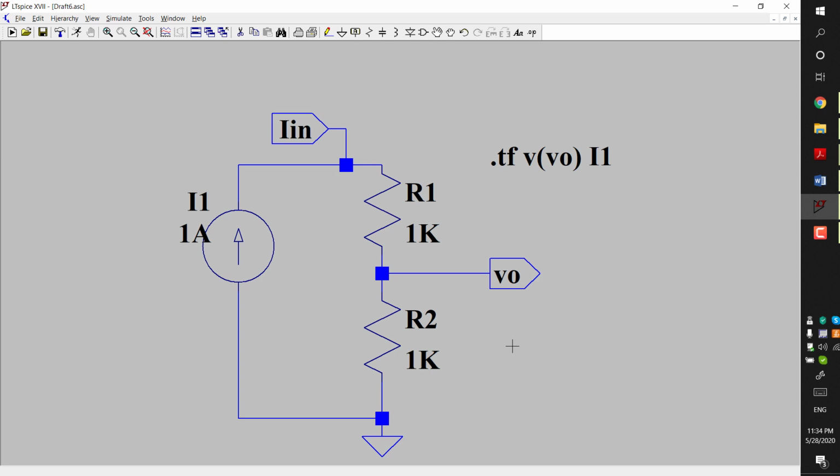In this lecture we've seen how to create a netlist, how to draw the schematic, how to run the simulation, how to perform different analyses, and how to theoretically investigate a specific circuit. It is always advisable to do some hand calculations with paper and pen before running the simulations, and once that is done, we can cross check our hand calculation with the simulated results, as we've shown over here.